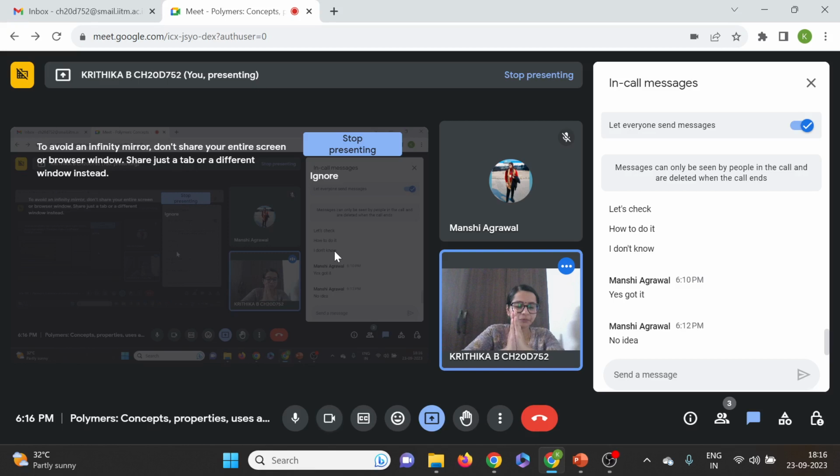That is, the interaction between the gum molecules within the gum has actually failed, but it has bonded very well with the material, for example your metal. Whereas when you see the exposed surface of the metal, for example here you are able to see some exposed surface of aluminum, or the exposed surface of stainless steel, in this case the adhesive has not stuck to that portion.